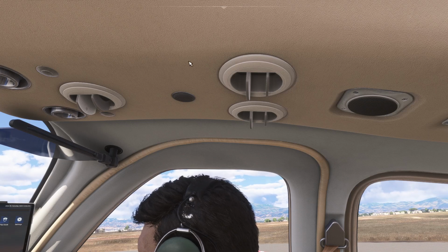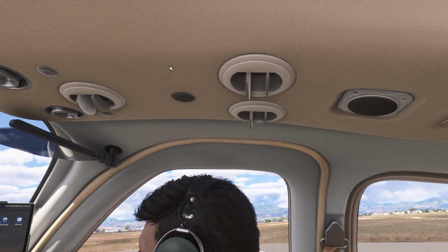These outlets are controlling the fresh and cooling airflow. We need to have them open to have the cockpit and the cabin cooled by cool air. The positions we set these outlets to are stored in local vars, so we have them for the next flight, any position we set them.